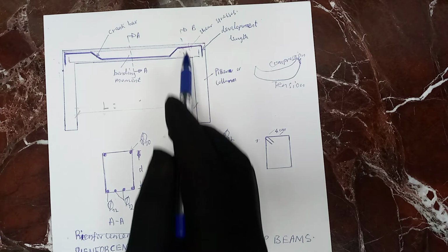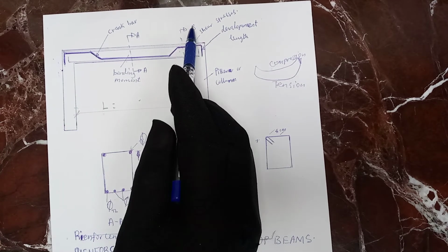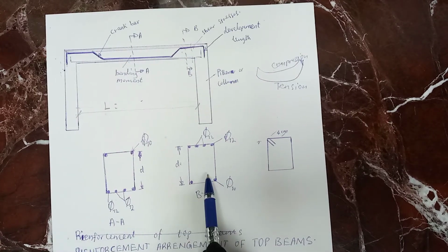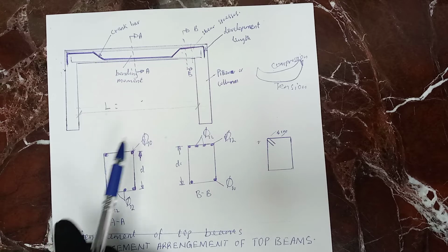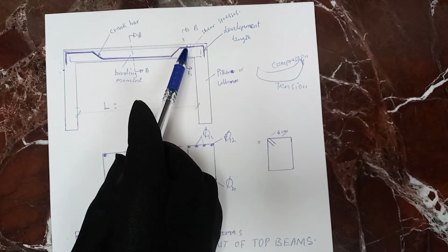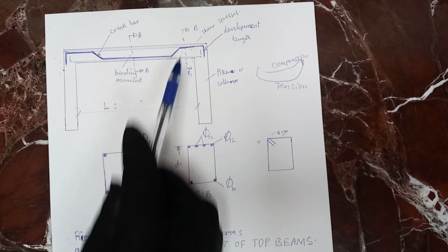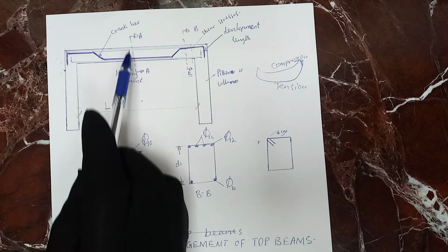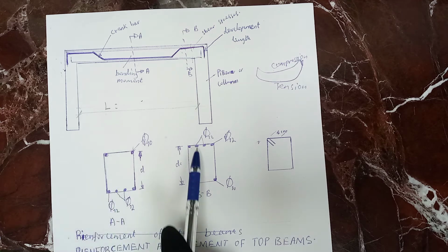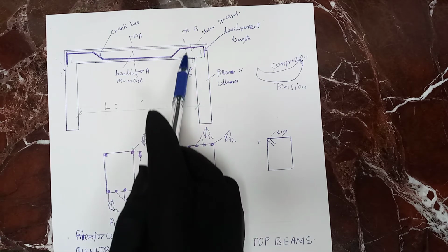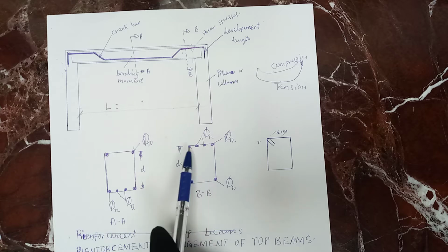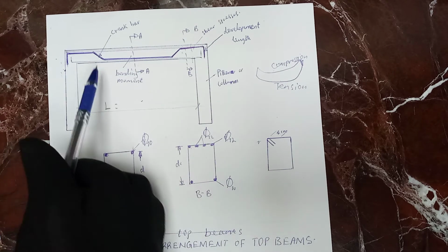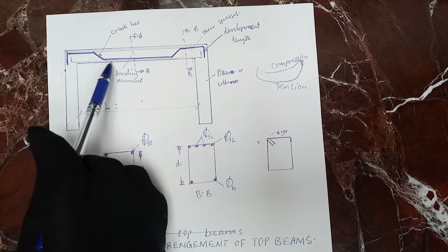And when you cut it again here at BB, because here is AA, this is what you are seeing. When you cut and look that way, this is why you see the crank bar. It is up. So that's why you see 4 rods up, and here you see only 2, because when you cut it here, the crank bar is down. But when you cut at BB, the crank bar is already up. And that's why you are seeing rod 12, 12, 12.